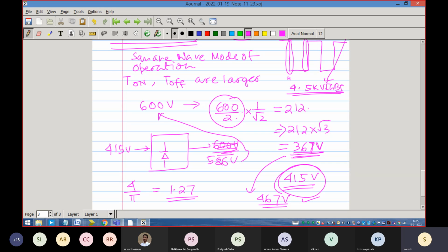You will get an efficiency of 80%. So 80% efficiency means 20% is loss. And what is the electricity cost of 20%? They have probably calculated it: the poor machine, let the poor machine die after 3-4 years. But on electricity, there will still be benefit in using the inverter at a very low frequency mode or square wave mode. So these are the practical issues that come in. Not all the time are the designs based on what is best possible.